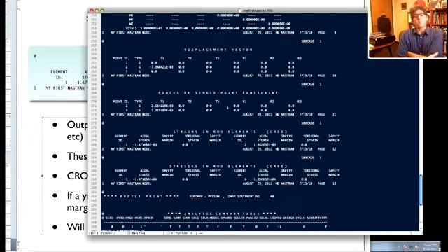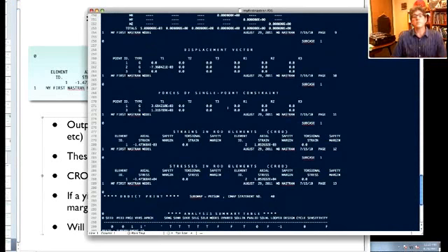Try to write the input file by hand. I mean, I posted the input file online, and you can use that as a reference, but I suggest that you actually write your own input file so you get used to the formatting and making sure that all the values sit in the right field widths. Run it. Look at your .f06 file. Make sure that the values correspond to the values here or the exact solution. Okay. You can use my exact solution if you want, but look through it.